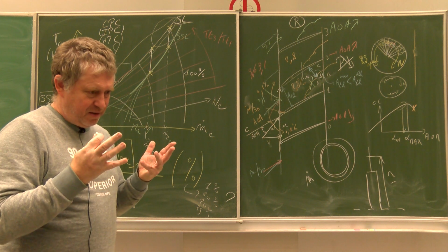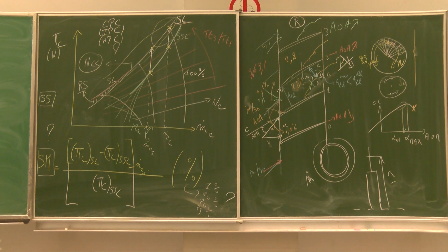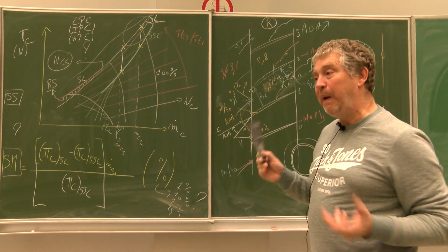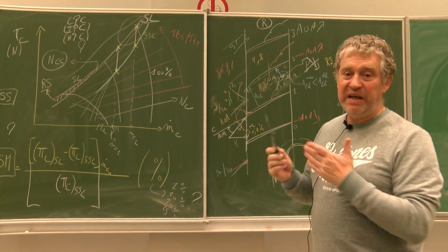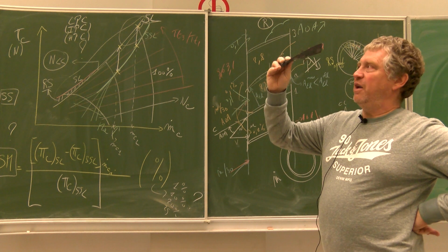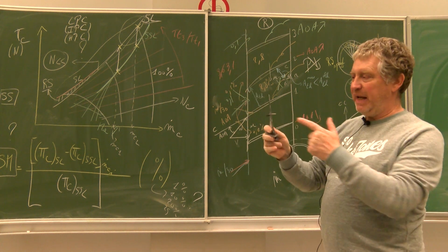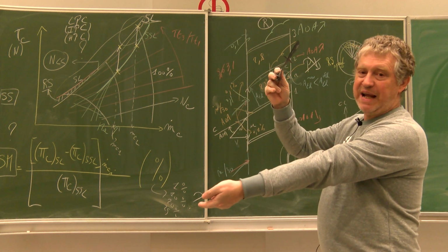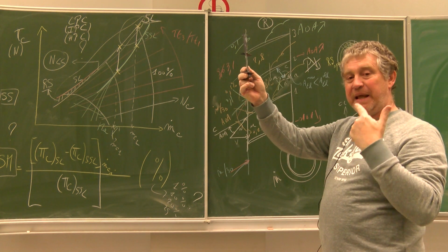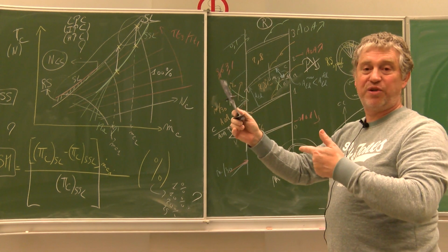But mechanically speaking, it will be a problem because this blade that is at the origin of the problem, or another one, because all blades are becoming the same with an impact of the stone or not, this blade is working in a right condition, rotating, rotating, rotating, and at a certain moment, the rotating stall cell is coming, and hop, impacting this blade, and then leaving. But this blade will see this rotating stall cell back later on.